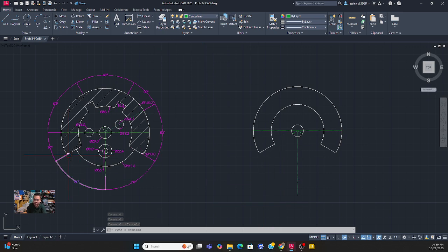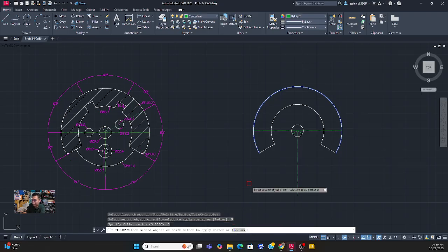I can also go ahead because I noticed that there's only 4 fillet corners. So usually I wait for the fillet to do it last, but to show you guys the problem, the diameter of that fillet is 10. So I'm going to go ahead to view fillet, first line, and then they ask me for radius. Well, if diameter is 10, radius is 5, enter.